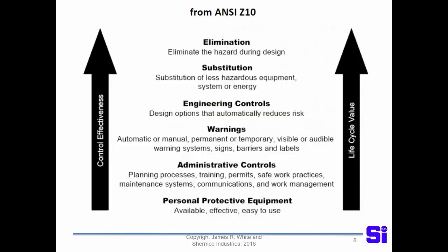And he said, really, when you talk about eliminate the hazard, you're talking about a permanent elimination and not a temporary elimination. So his point was eliminate the hazard during design. And then substitution, substitute less hazardous equipment, system, or energy, such as reducing the voltages, putting in control transformers.